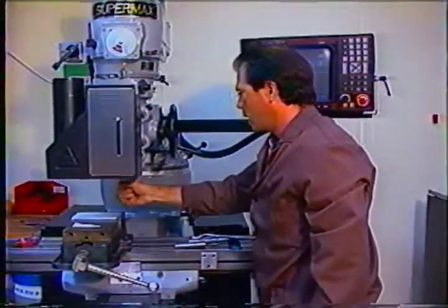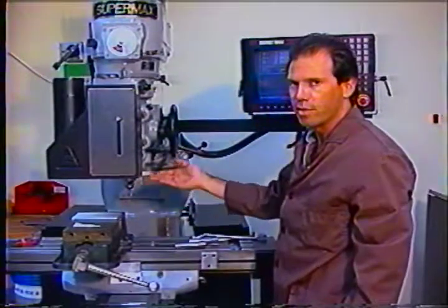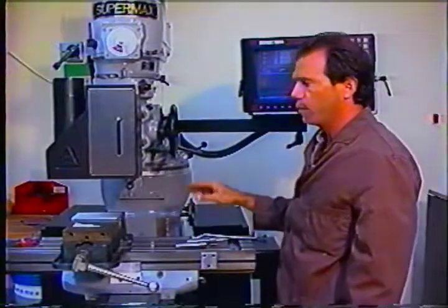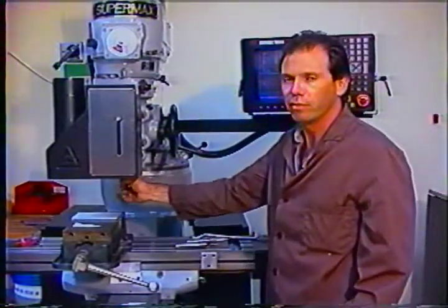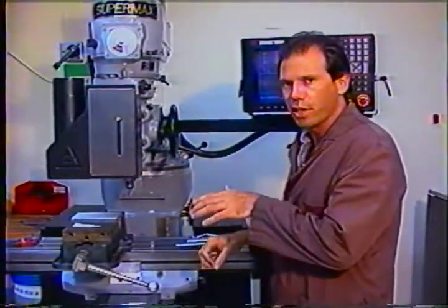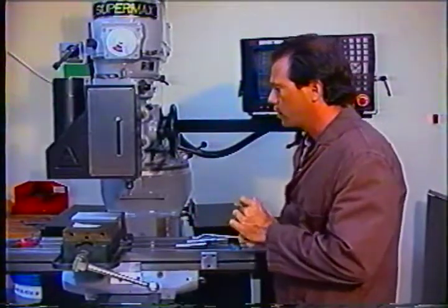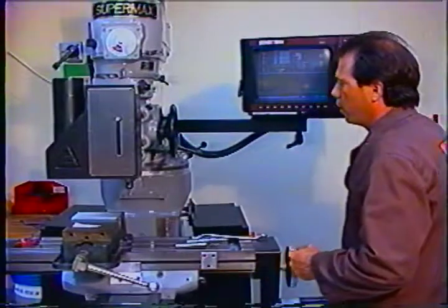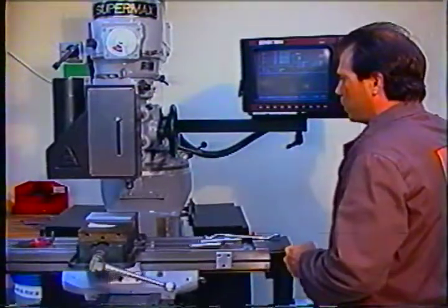This tool being an actual end mill holder, I can repeat the Z position with it. Normally in a retrofit like this, you'd have a quick change spindle where the tooling will go back into the same position every time after every tool change, therefore maintaining the correct offset all the time. So we'll jog back over the workpiece,